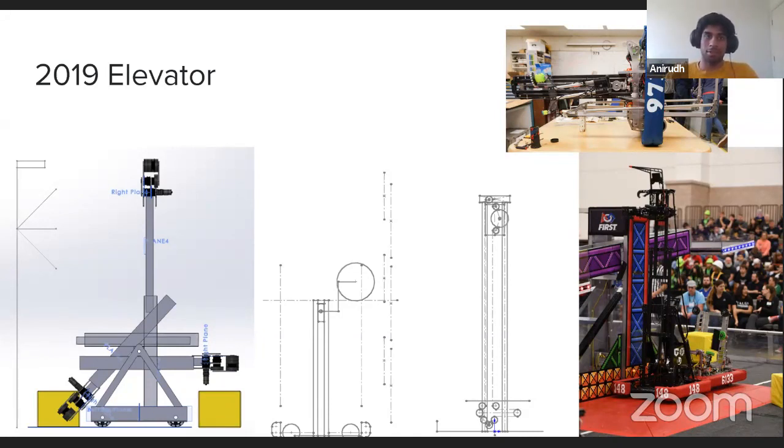The next question: any advice for a team with a CNC router during the prototyping phase? One thing our team has found really helpful is making prototypes out of wood, because you can do that very, very quickly on a CNC router. Generally, as an FRC team, you want to use all the resources you can. So you can make some pretty high effort prototypes, which can be very close to your robot and can answer a lot of questions. And you can very quickly prototype using wood on CNC. Do you have anything to add, Rashawn?